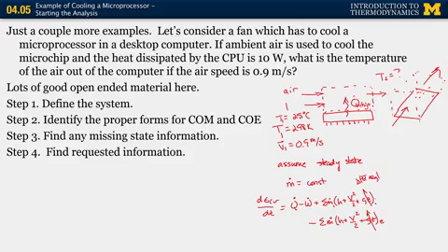But the wind speeds, the air speeds we're talking about here, are small, so you might expect the kinetic energy effects are going to be small. Again, it's steady, just like in the conservation of mass, so we better have that simplified. We know there's heat transfer. There's no work transfer within this control surface. There's electrical work into the chip, but that's not our system. That electrical work is being used in part to create this heat transfer.